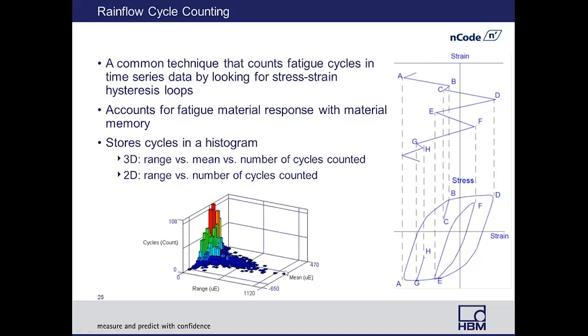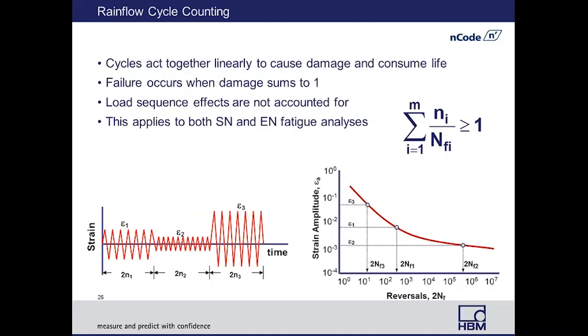All right, so we need to come up with a way to accumulate the damage. And the best way to describe this is just to take that block cycle loading example that we saw a few slides ago. In this case, we've got 3 different strain levels that have 3 different numbers of cycles associated with each of those blocks.